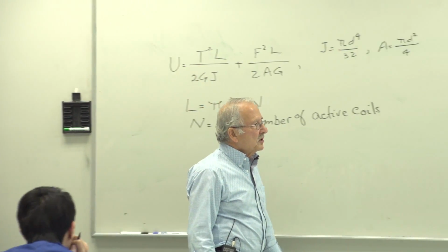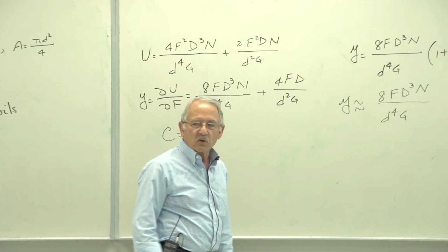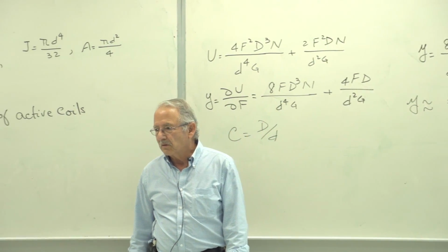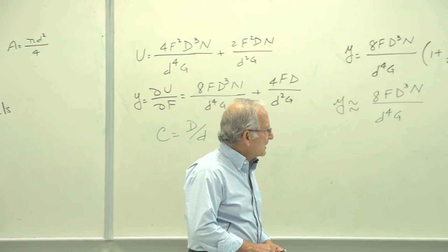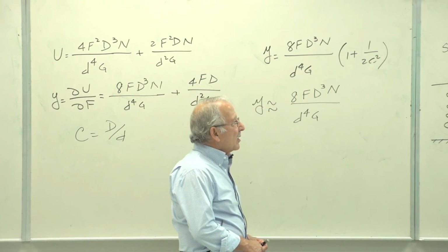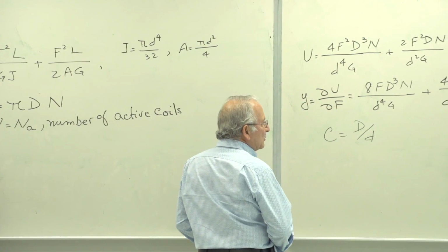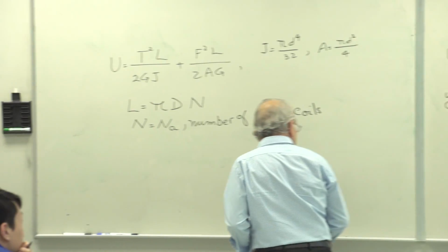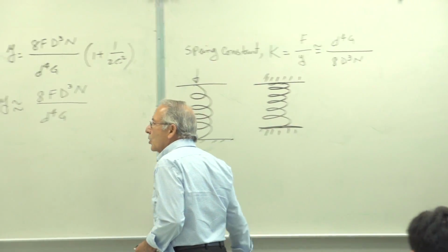I would just simply take off 2 coils if you're here or here, 1 if you're here, and none if you're there, and not worry about these equations to try to apply them exactly the way they are. The free length of the spring, as the name implies, is the length of the spring with no load on it.